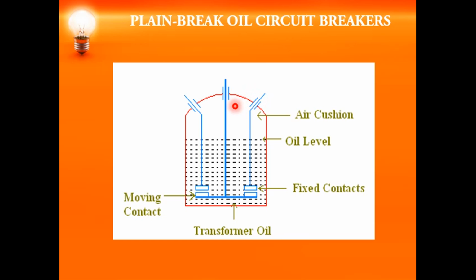And you can see you have a vent which is provided here. That vent is nothing but the gas outlet. So you should see to it that the pressure is maintained within the prescribed level within the tank, so that it never gets damaged. So the arc quenching factors will be lengthening of the arc, that is, the elongation of the arc. The formation of the gaseous medium will produce a high dielectric strength, and the oil movement also will try to quench the arc.